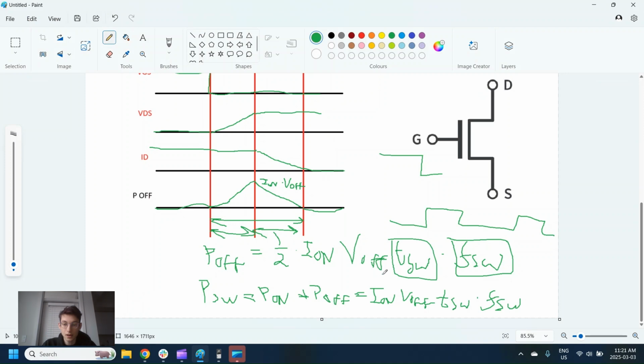And we can see that these are going to scale. I mean, of course, higher currents, higher voltages are going to lead to more power losses. That's normal. But the thing we're really worried about here, when we're selecting something to reduce that, is the time. How long is it going to take for you to open and close the switch when you send that signal? And if it takes longer, you're going to have more power losses.